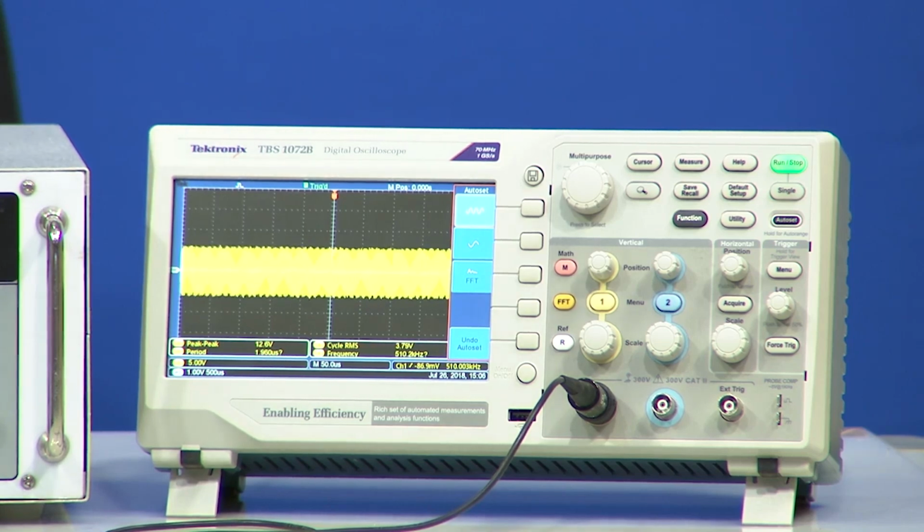As you can see, the output voltage is coming down. You can maybe go till around Vm by root 2. You can put a threshold value till where you want to consider that this output is good enough for your applications. Finally, it's about your own choice, like the further circuits to which you want to connect. Let's say your ideal output is 16 volt, but you are okay with working till around 13 volt. You can go on to higher frequencies.